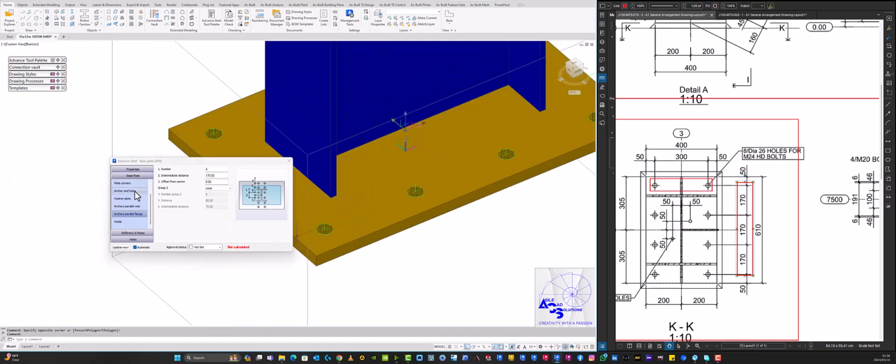Then from there, we go to welding symbols. Welding at the web, it's 6. Welding at the flange, it's 6. Fillet welding, which is exactly what we want. If the welding has changed, maybe to 8mm or 10mm, this is where you edit it, and the type of welding as well. This one, I'm going to leave as it is. It's perfect. Then we go to stiffeners.